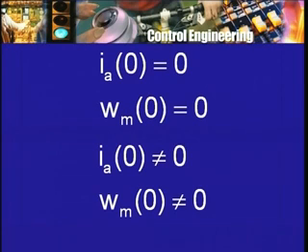So the problem is, given a system or a set of differential equations, in this case linear differential equations with constant coefficients, given the specific input functions, the behavior of the variables EA and TL, maybe both of them are kept constant, or one of them, EA, is kept constant and TL is varied in a certain way, or both are changed in some specific ways. Knowing how EA and TL are going to change with time, knowing the initial values, obtain or calculate or find out omega m as a function of time and perhaps Ia also as a function of time.